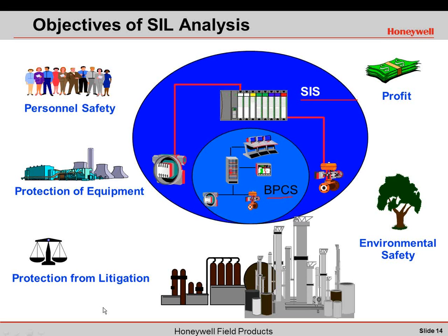All right. The next question, can the safety controller and the process controller be the same device? No. Let's say I had two HC900s. I could configure one of them as the process controller, and within an HC900 we have two ways that it can be programmed, one for process and one for safety.